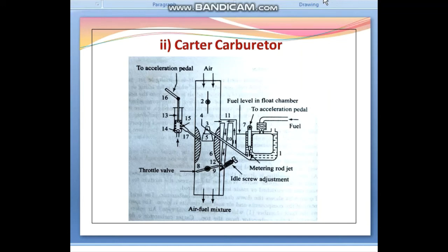The combination of gasoline and air is drawn into the nozzle chamber through the jets on the side of the nozzle, forming a fine spray which is carried by a standpipe to the venturi or main pressure passage, where it is absorbed by incoming air, forming the mixture on which the engine operates.